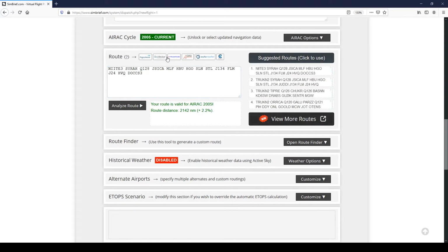And this is how a flight plan is given to us, and also how it's entered into the flight management computer of the aircraft. So this over here is the departure route. Each departure route has a name. This is our arrival route. And these over here are all the waypoints and airways that we're going to have to follow along the way. So this thing over here is a waypoint name. This here is an airway.